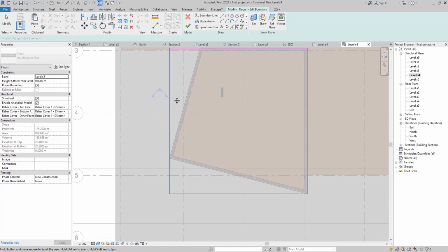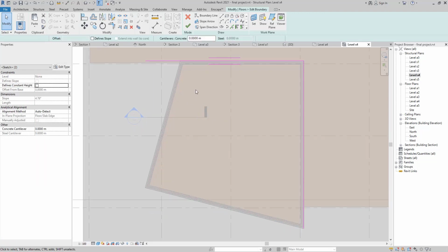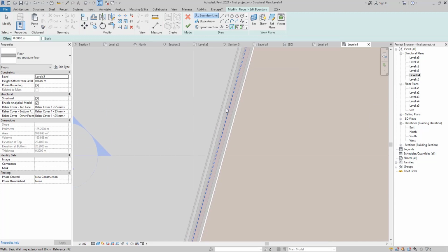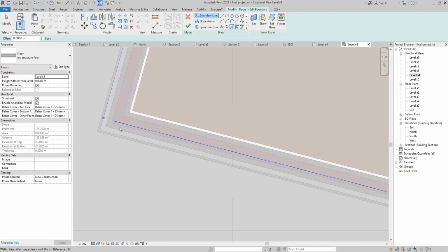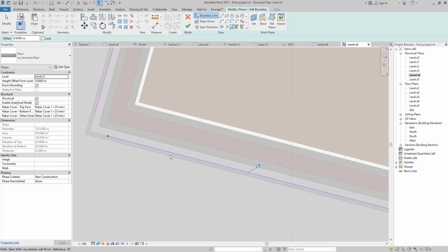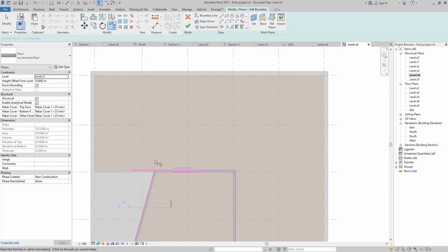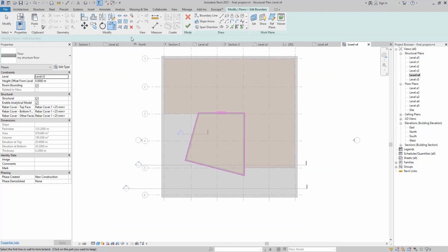So we align our line, but align is not going to, for example, work like this. It's not going to change the angle of the line. So what we need to do is to draw it by ourselves or pick a line. So we are just going to delete this, and we are going to use the pick line here. We are going to click this line, and here as well we will find the line. Okay, then we are going to use trim with TR to close our object, and everything looks fine.